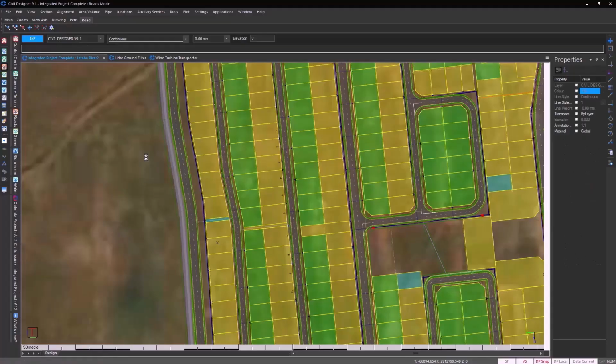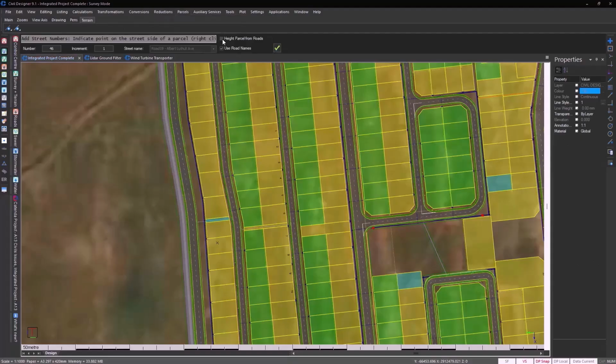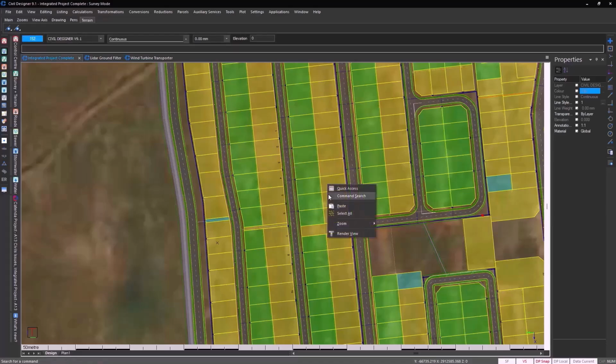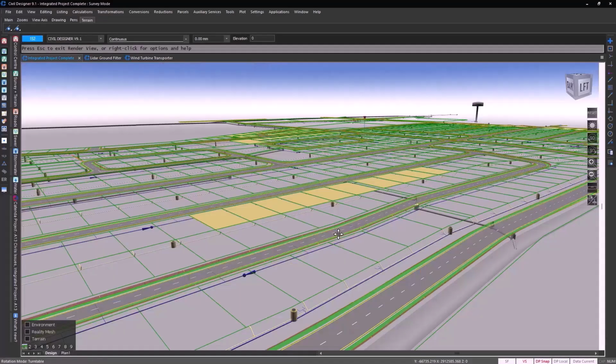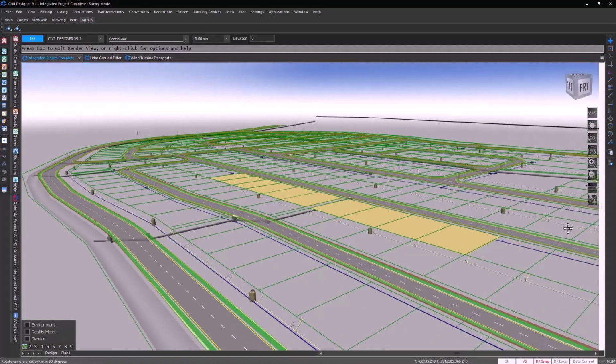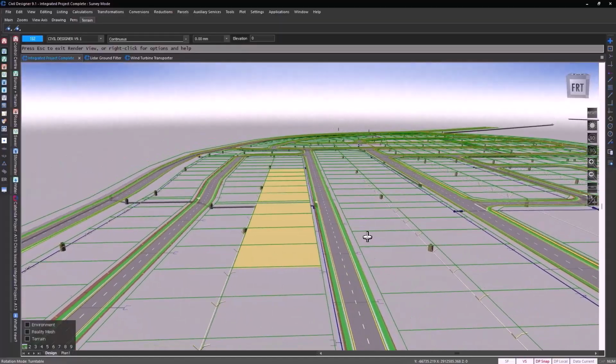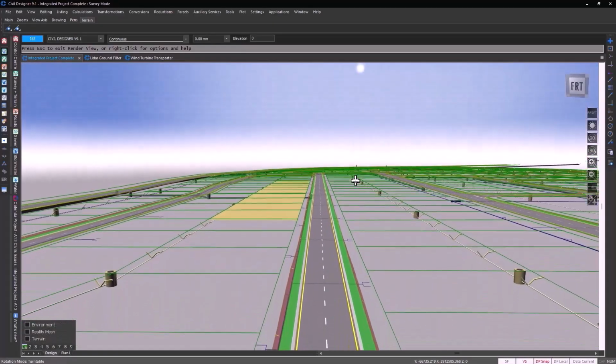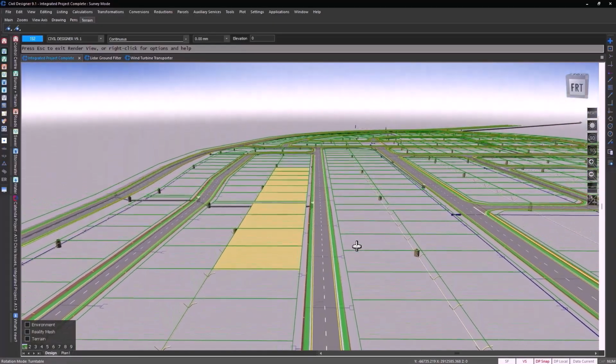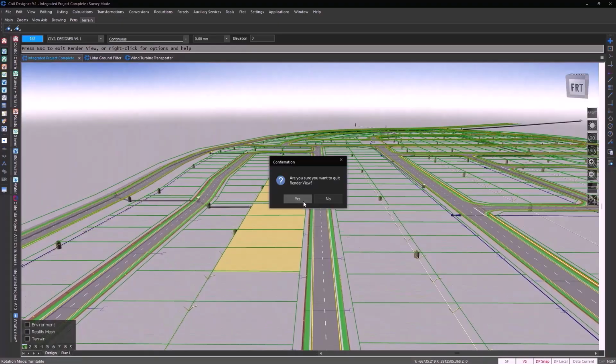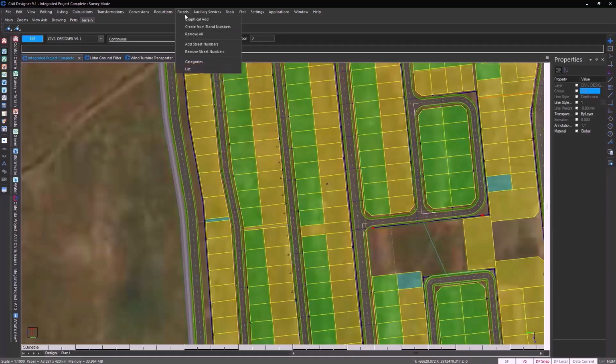While still in the roads mode, a function that has gained popularity and created lots of excitement is Parcels. In this newer version, Civil Designer can automatically assign parcel heights from maximum elevations picked up from the adjoining roads. Elevation constants can be added. If these adjoining roads' vertical alignment changes, so does the elevation of the parcels, giving them a dynamic 3D elevation. The parcel road linkage relationship can be edited from the properties bar. Parcels are now also included when we export to shapefiles.